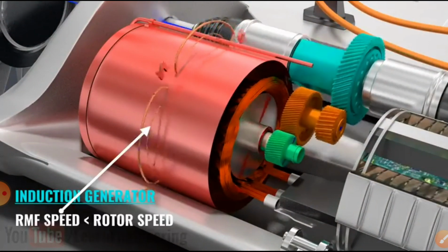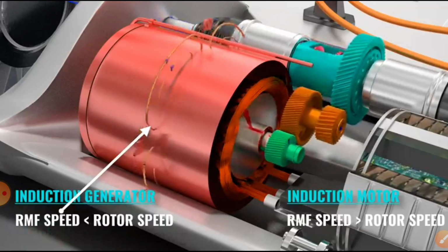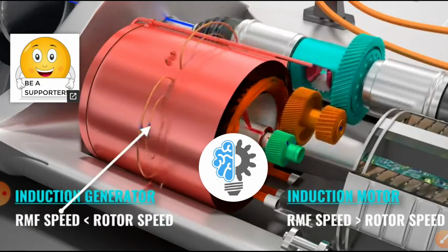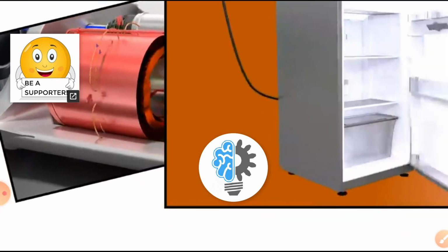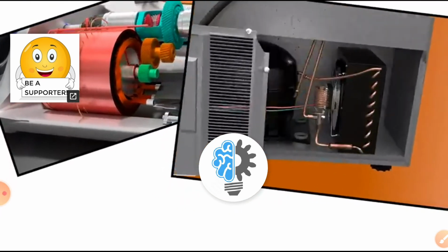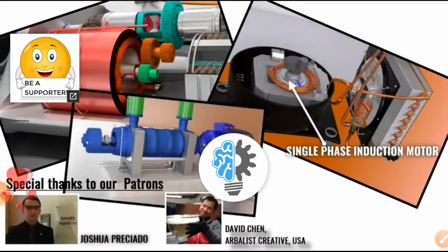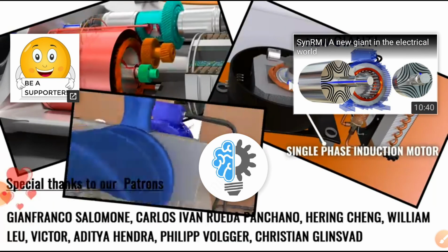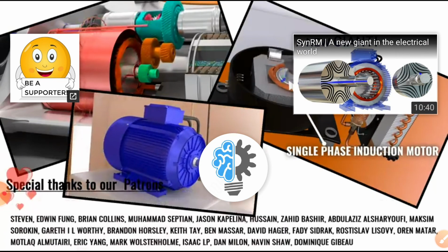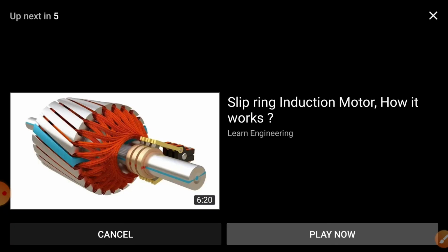What do you mean by the induction generators? In this case the rotor speed is greater than the synchronous speed, then it becomes a generator. Okay, so if the speed is less than the synchronous speed, it will act as a motor. If the rotor speed is greater than the synchronous speed, then it will be an induction generator. Generally this can be used in windmills also. So it has different applications, you can see here. Okay, there are plenty of applications we are going to see in our daily life.